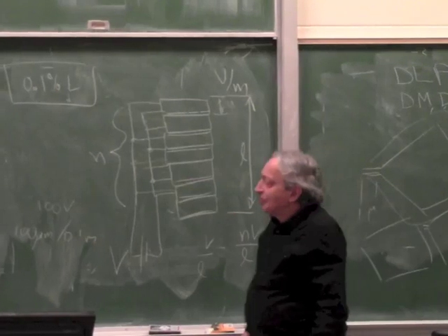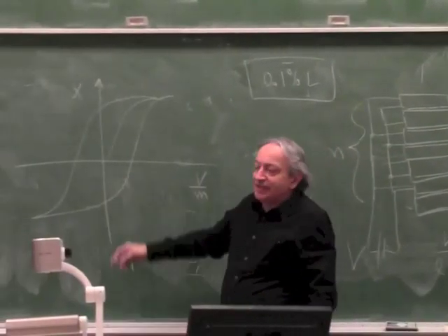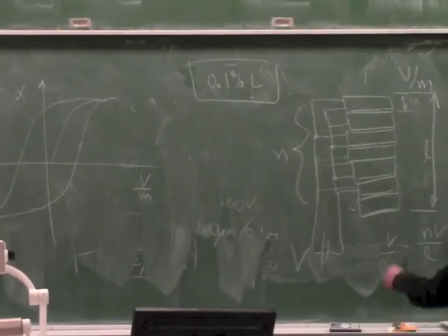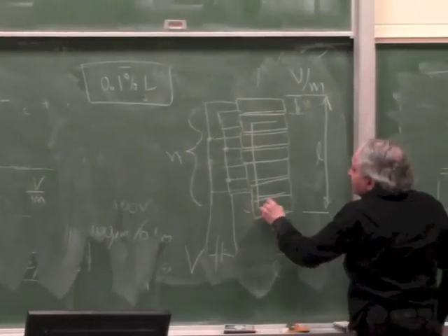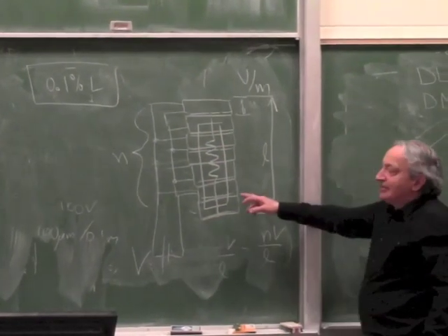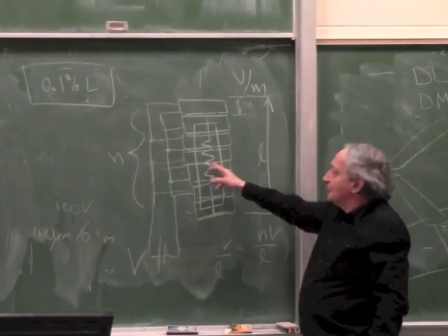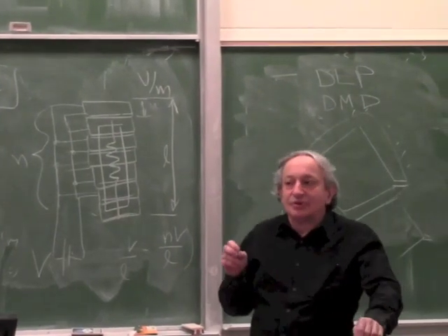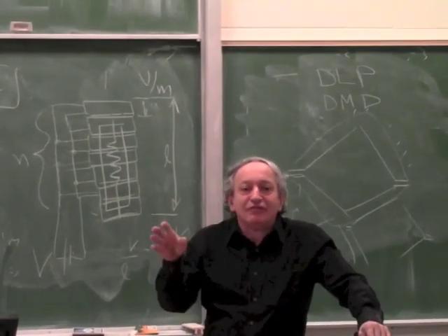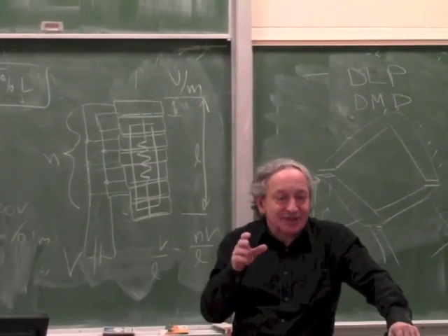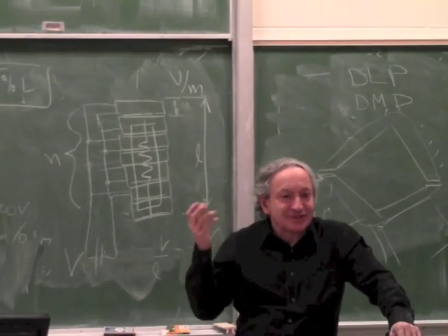Now the second problem, that it has hysteresis, is a bigger problem, and usually it's solved by sticking a strain gauge on the whole stack and closing the loop with the strain gauge. So when you want the stack to move 55 micron, you don't give it 55 volts and say move 55 micron, because of hysteresis.